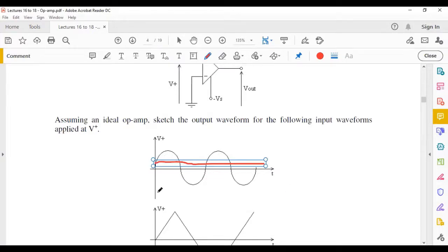What's the result? So basically now in this region there, whenever you're below that line there, so this is what I've drawn here is your V minus, which is set now at 2 volts using a voltage divider circuit. How can you do that? Very simply, you could just use a voltage divider with a resistor here. You can just do a voltage divider.